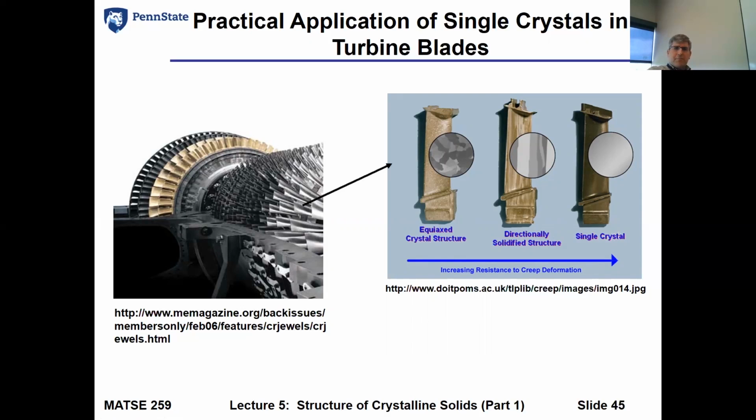When these blades were initially developed, most everybody tends to think, especially in polycrystalline systems, that we would need an equiaxed crystal structure. What that means is you have a multitude of different crystal orientations, and these are called grains. They allow us to produce what we consider to be the strongest material when we think of forged materials.